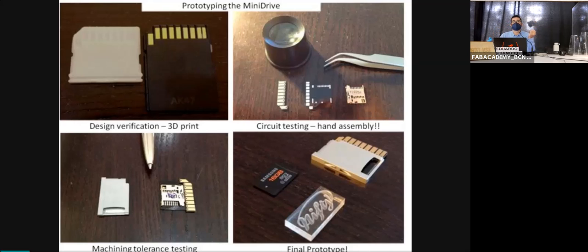So this is about prototyping stages. You first 3D print your prototype. It's cheap, easy, and you can do it really fast. And it's really comfortable to do. So you print your model until you get good tolerances. Of course, the tolerance between a 3D printed part and a CNC part are slightly different, but it's something that you can accommodate through the prototyping process.